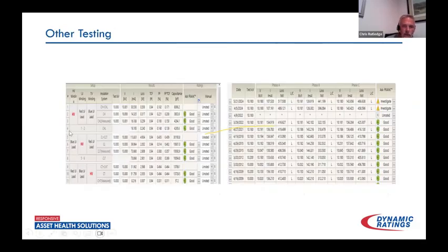So some offline power factor tests are run, and we see that, yeah, we're looking pretty good here. Nothing's changed in the power factor that much until we go to excitation current. And we can see that we were high, low, high on all our excitation, but running quite a bit of milliamps, 156, 143, 156.